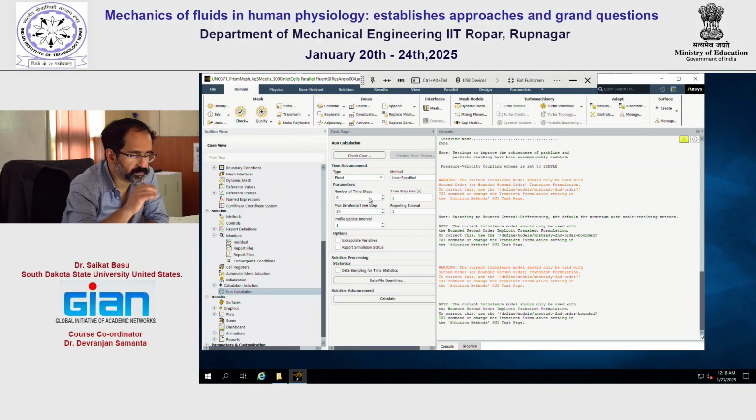So over here, let's think about the time steps that we are going to use, and there are a couple of papers on what you need as the proper time step size. There were a couple of publications back in the early 2000s, 2010, 11, where they looked at geometries as complex as this one, and they tried to figure out the best possible time step, in the sense that the longer the time step, the quicker the simulation would be, right? If you're trying to track a certain interval. So for 30 liters per minute, the consensus was the time step should be 0.0002.